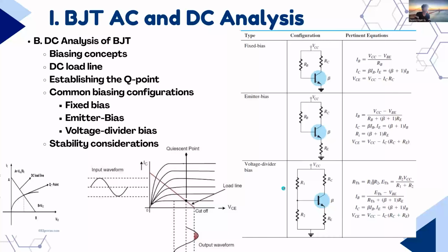It uses two resistors to form a voltage divider at the base terminal, making the base voltage fixed and independent of the transistor's internal parameters. It will offer the highest Q point stability against variation in gain, because a BJT can vary its gain with temperature.